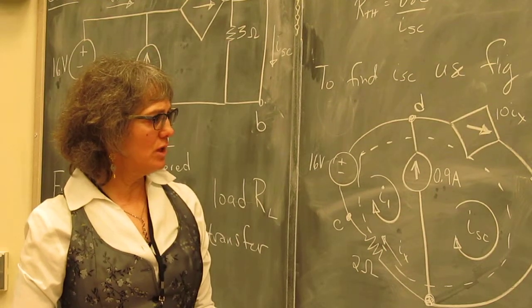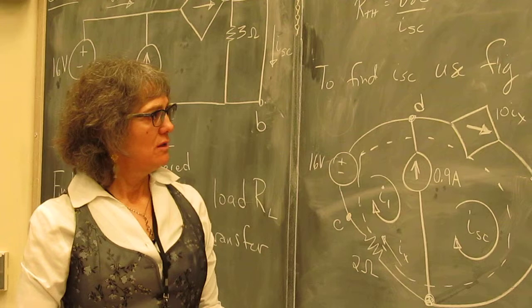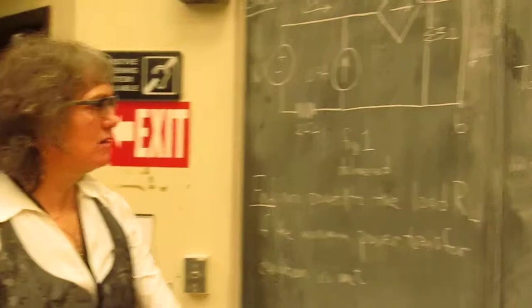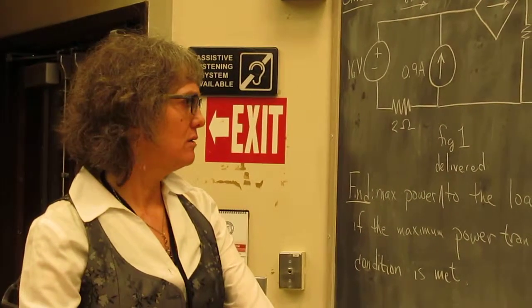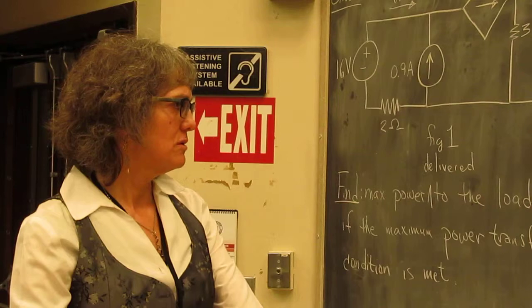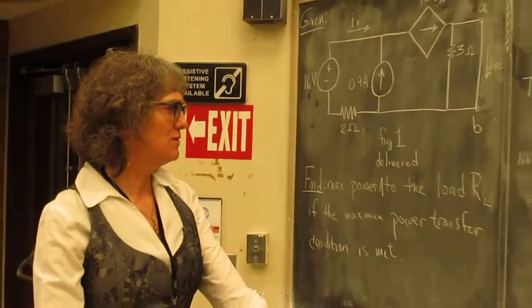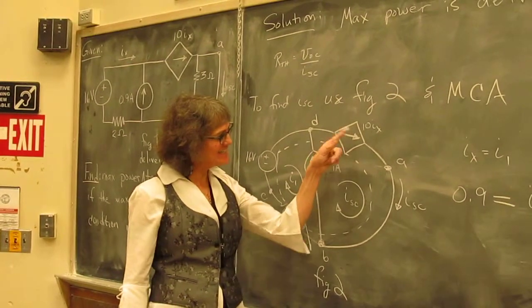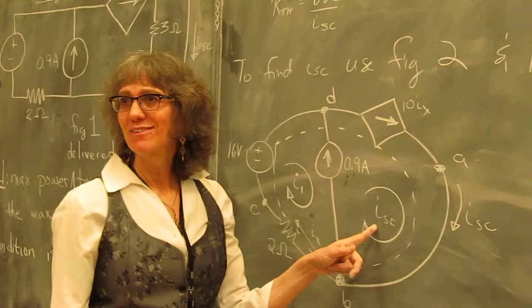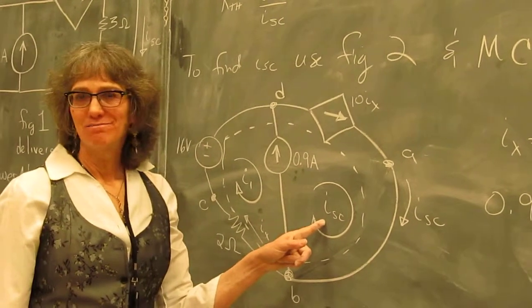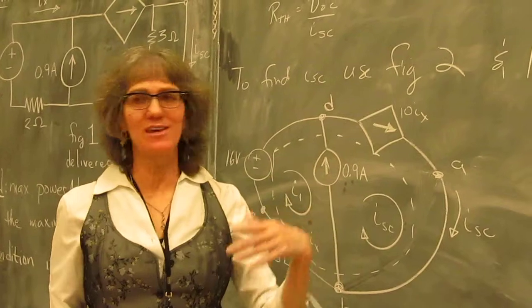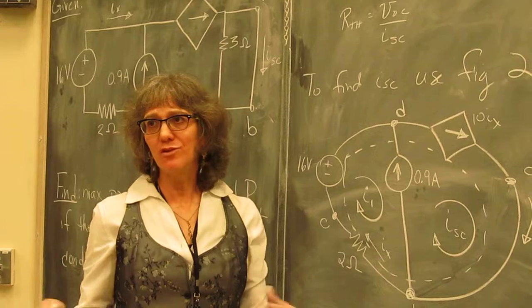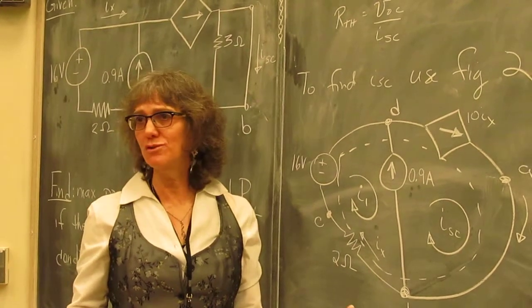So actually, we're not even going to write Kirchhoff's voltage law. We're just going to notice that the current, wait. I actually did this with node voltage analysis. So let me see what's going on here. Oh, this is a weird problem. Okay, because this current source is ISC. Okay, so we didn't even do Kirchhoff in this case because we only had one mesh and it had a current source on the perimeter, so you don't do Kirchhoff's voltage law in that case.